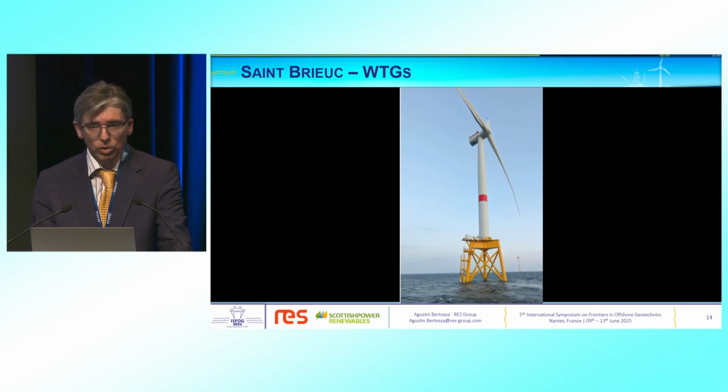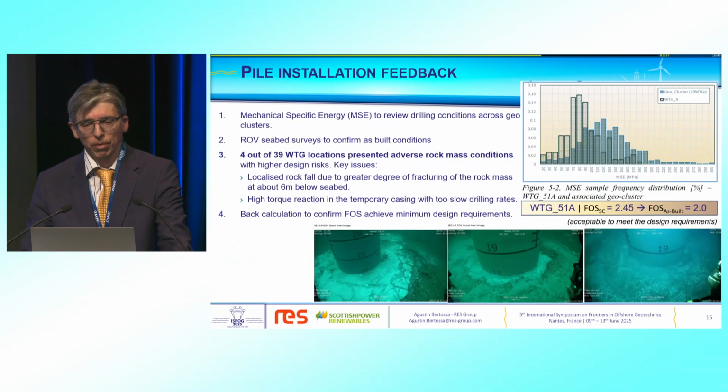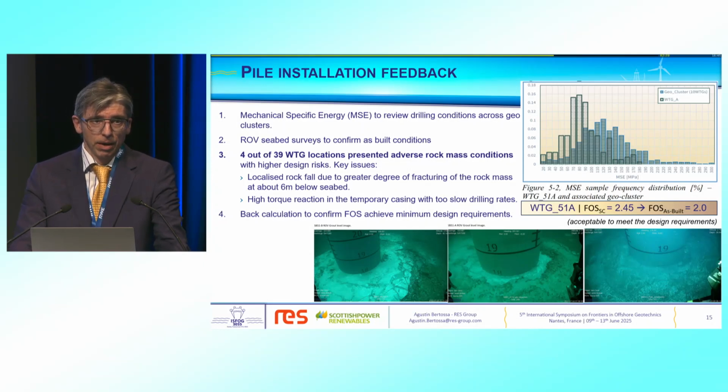Once the installation was complete, we reviewed the data from the drilling records, and the feedback was 4 out of 39 locations presented issues in the drilling. These were through either excessive refusal in the temporary casing, or evidence of overbreaks or lower mechanical energy.